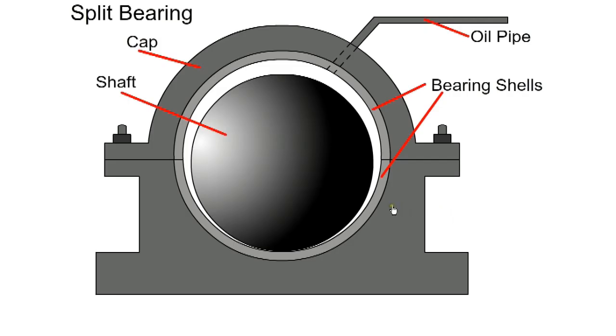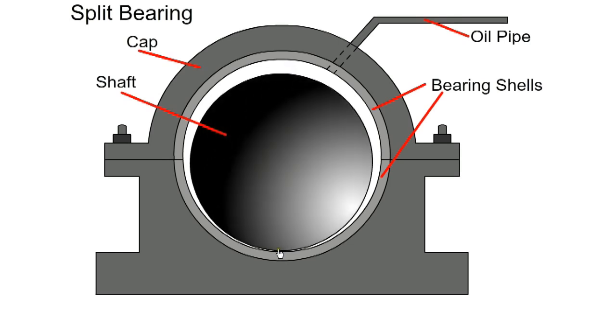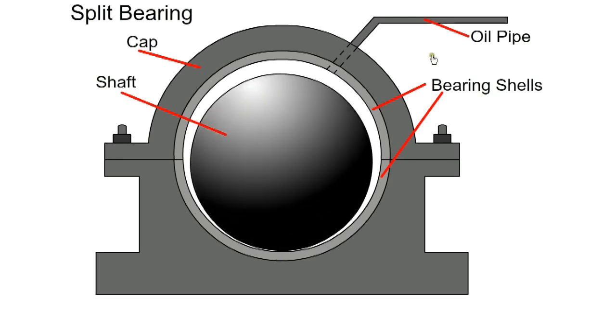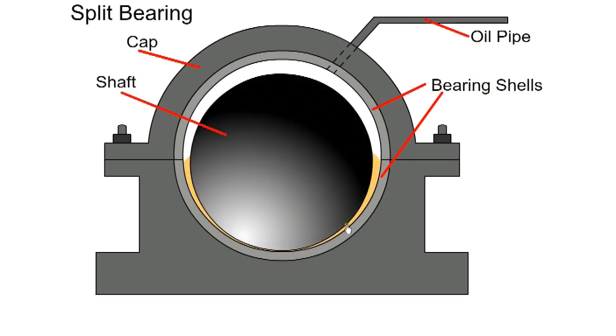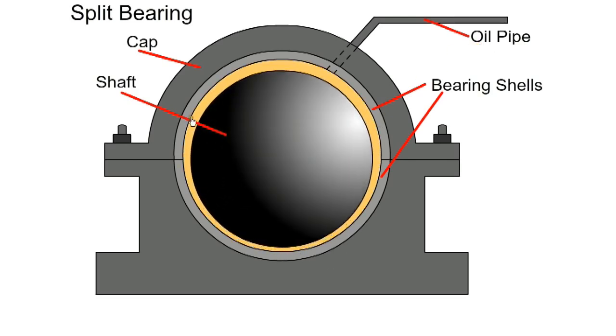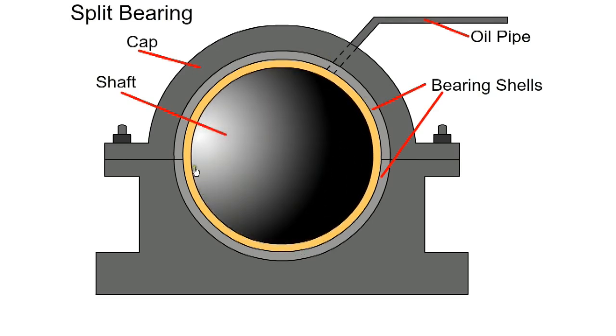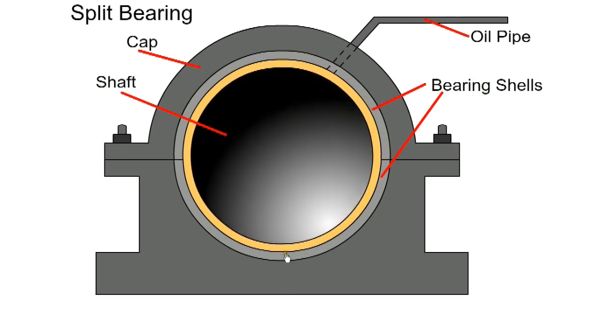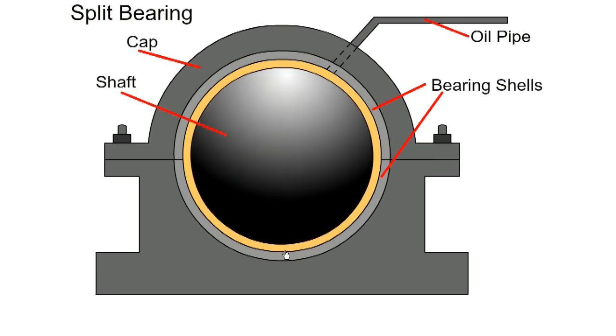The bearings in an engine use hydrodynamic lubrication. There is a very small clearance between the shaft and the bearing journal. When the engine is started, the shaft is running without lubrication for a short period. When oil is introduced, a film of oil is dragged around by the shaft and the shaft is then centered in the bearing housing. Now we have hydrodynamic lubrication.